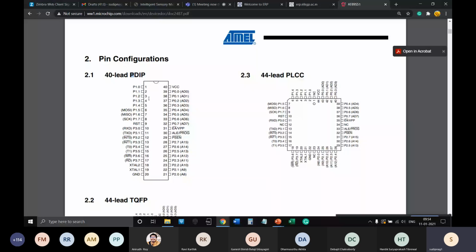Earlier, the old 8051s by Intel were developed on ceramic, because ceramic offers better heat dissipation and the chip used to heat up. But today's microcontrollers have better circuits and technologies, so not much heat is generated. Plastic is a bad conductor of heat, but it is good enough because the chip stays almost as cool as room temperature.